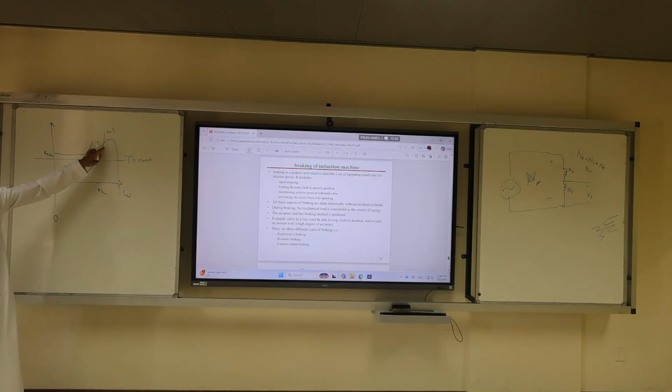If you connect a fan or the linear torque, you're in the unstable region. So you have to change the control of your motor to cross it where? In the linear region. In other words, three different loads require three completely different controlled parameters. Is it clear now? Yes.